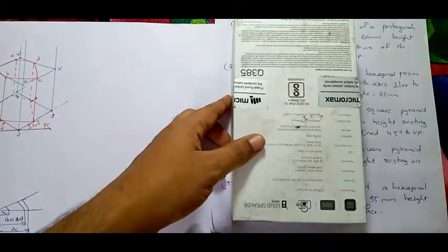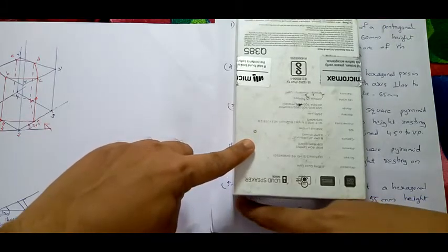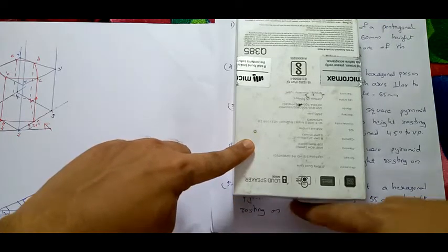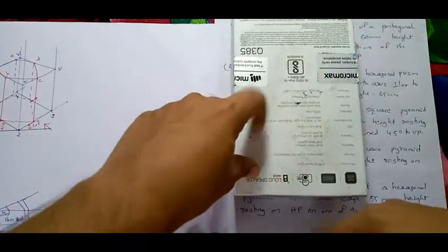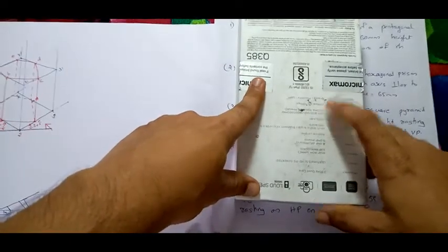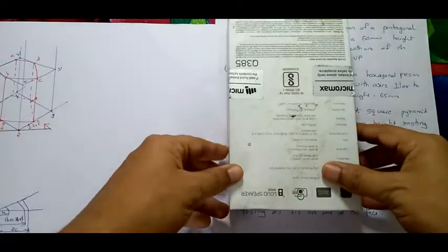So the thing is, if you are placing like this, no need to rotate. This one is your base, so the hexagon is here itself. From front you can see the hexagon, from top you can see the rectangle, right? So you can directly draw this. How to draw this, I will show you here. We are drawing this front view, top view.